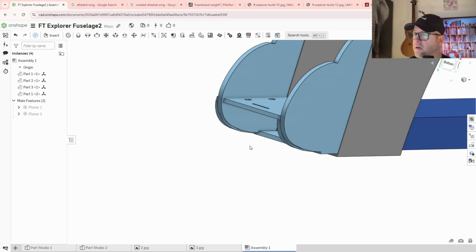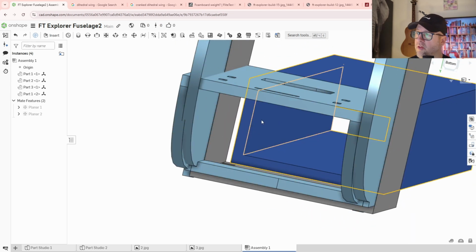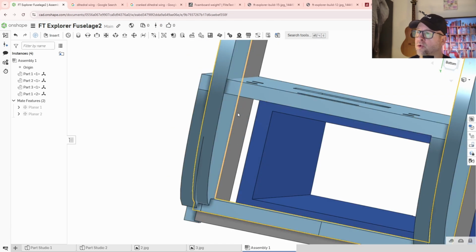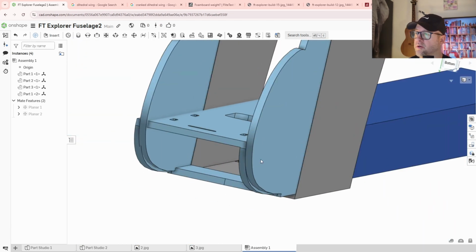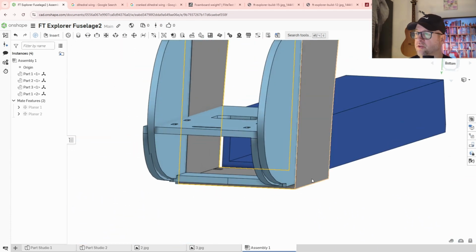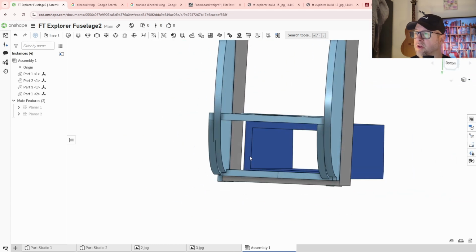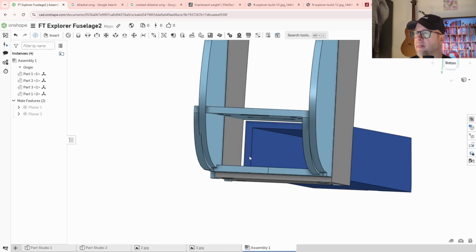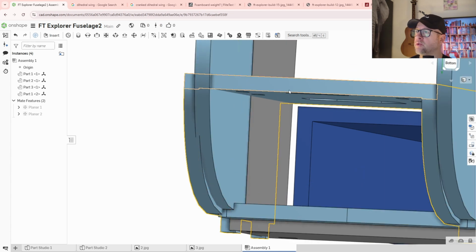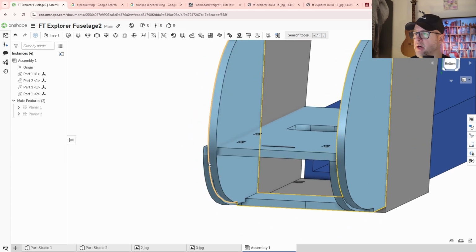This seems a little bit thick, so it looks like we need to adjust the thickness of that by a little over 4 millimeters. So we're going to pull in this wall 4 millimeters. So one of the trims or something that we did was a little bit too big. Okay, so that means we can actually just grab that body and might be able to get in here and make it smaller by 4 millimeters.